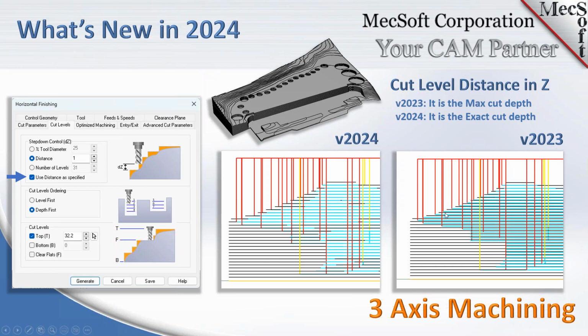Yeah, and also just look at these two images. The one on the right is in version 23, where the cut levels didn't fall exactly at the depth that the user specified. In this case, which is a distance of 1 millimeter. If you look at this example part, it's a topographical stack of surfaces at 1 millimeter intervals. So now you can actually set the distance at 1 and check this box here, and it'll maintain exactly that distance, as you can see over here under the 2024 image.